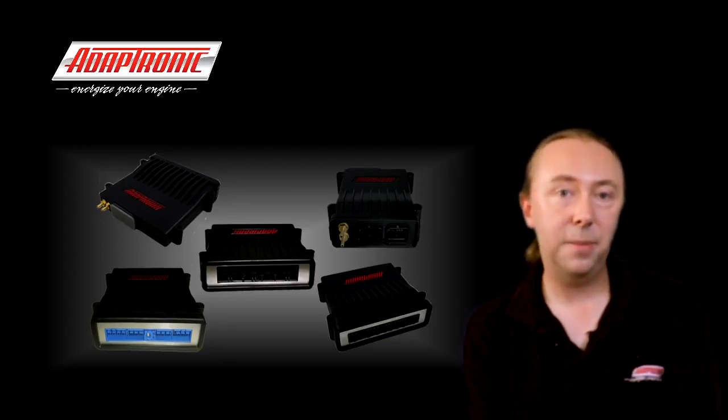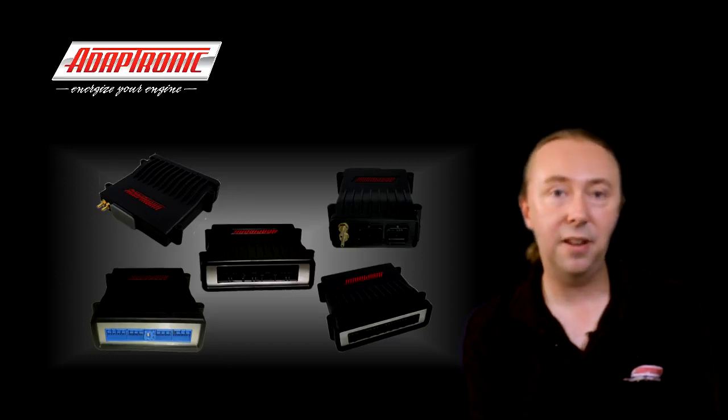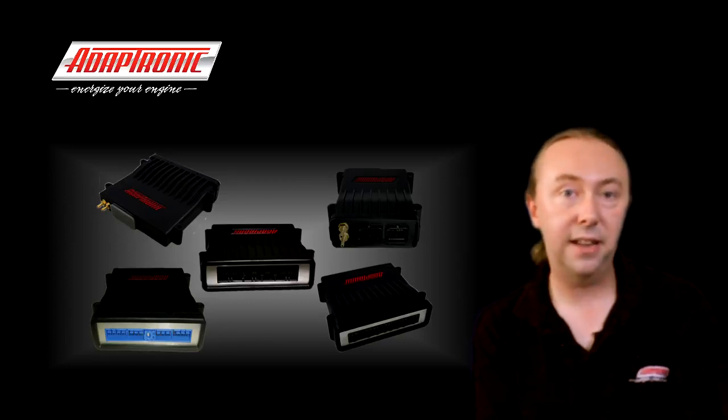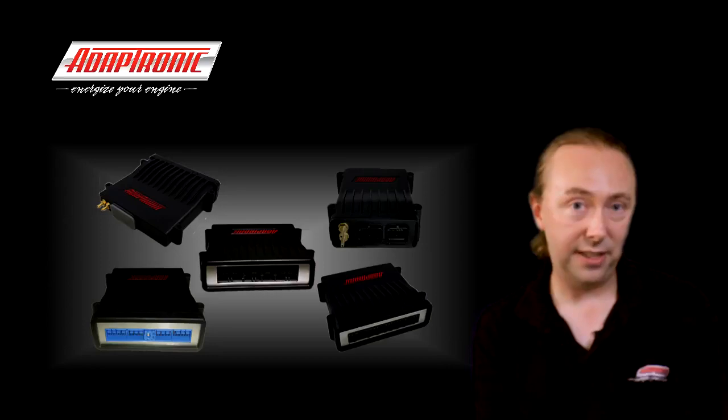In this case, the 2 banks can each have their own map sensor, and also if you're running pressure ratio, they can have their own exhaust manifold pressure sensor as well. So this is particularly useful on dual plenum engines like the VG30 and V12 engines, because often the pressure in each inlet manifold is not exactly the same. So you can, even with balance pipes, run a separate map sensor on each one using, say, the 2 inbuilt map sensors in the ECU, and you can run each half independently. You can also run the individual boost control on this sort of engine this way.